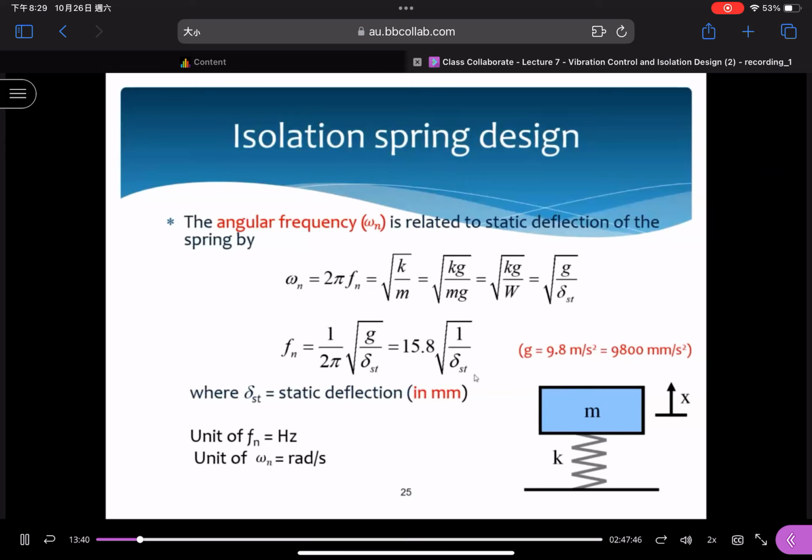I just want to share with you that here we have three cases: over damping, critical damping, and under damping. Okay, in our study, we just focus on the last one. The reason I explained it before is that for the first two types, over damping and critical damping, no oscillations occur, like this one, like this one. Okay, we use zeta, the damping ratio, to identify which category we are going to consider, whether this is over damping, critical damping, or under damping.